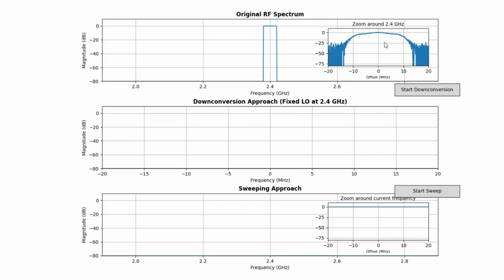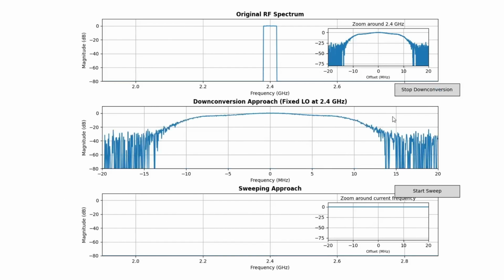And especially for dealing with digital sampled signals that are from output of ADC, we can use FFT, which is the fast Fourier transform, to get the frequency content. This is the first approach which we are going to take in this video.